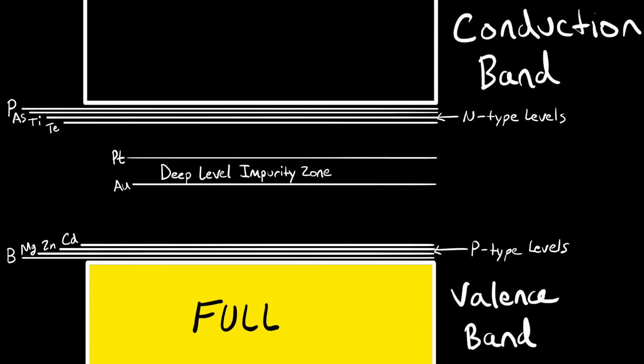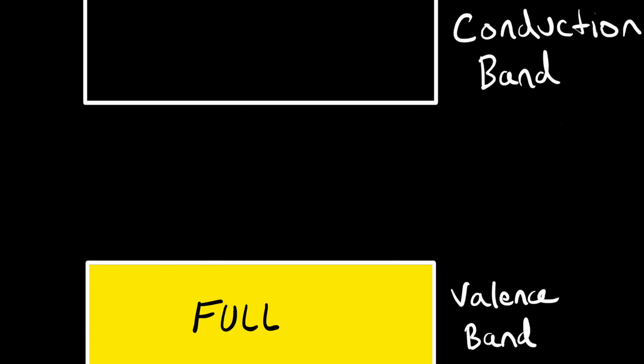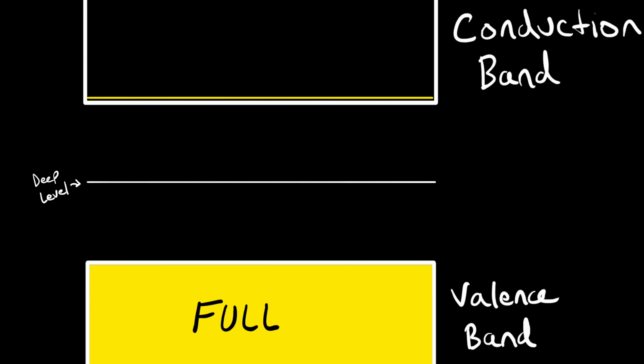Remember that each orbital corresponds to a location within the silicon lattice. Let's start with pure silicon. Let's say I have an electron with enough energy to be in the conduction band, here. That means that the electron can freely move between any of the billions of other orbitals at the same level. However, let's say that we have one of those deep levels. If there happens to be a single vacant energy level that is significantly lower, then the electron will preferentially fall into that level and release some energy. Now that electron is trapped until it gets enough energy to jump back up to where it was before. Eventually, that will happen, due to thermal energy, resetting the trap for another electron.